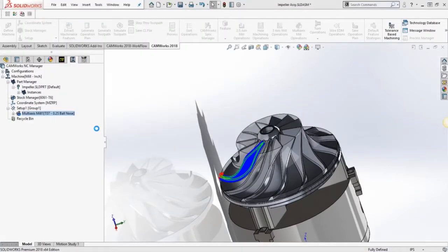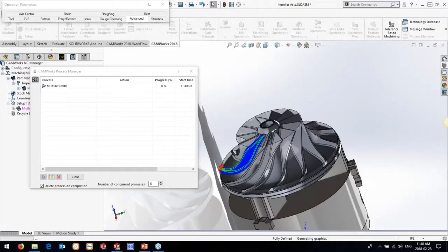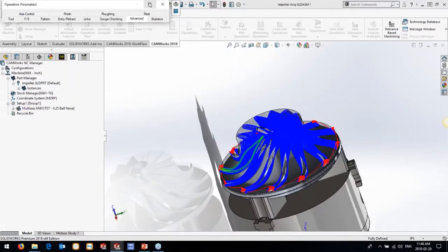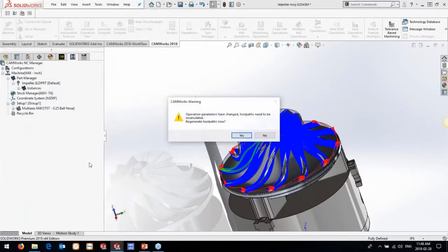So full 5-axis simultaneous. You can do all of your B-axis if you're sticking this on a B-axis indexing lathe, B-axis Integrex or something like that, or a NTX 1000, something like that. Then basically you can do all of the full 5-axis simultaneous milling on your live tooling lathe as well, and get all the complex stuff going on there.